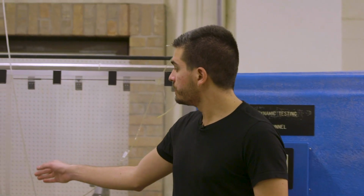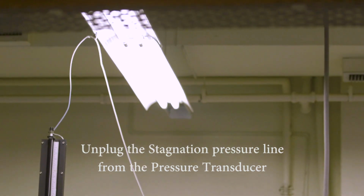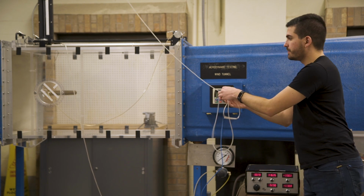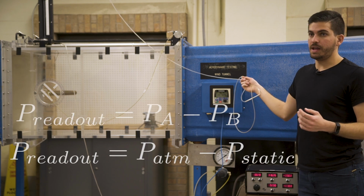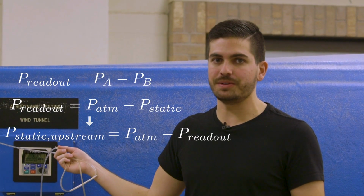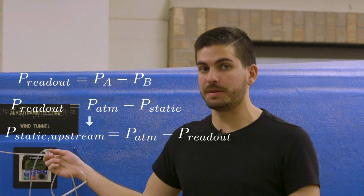So what we'll do is unplug the stagnation line, which is at the top of the pitot-static probe. We'll follow this and unplug it from the pressure transducer. After we unplug that from the pressure transducer, we have in port A the atmospheric pressure, in port B static pressure. So now we have on its own a measurement of static pressure. And so during this, we'll record both the static pressure and the dynamic pressure upstream.